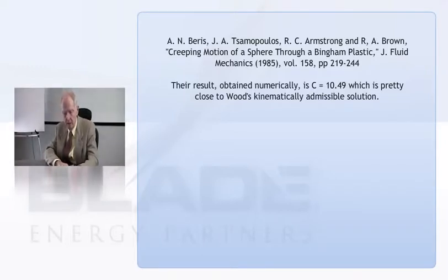And I think that's also reasonable, because when you're guessing a stress field, particularly in three dimensions, you've got to satisfy all the equilibrium equations, and that gets to be a little more difficult than doing it in two dimensions. So anyhow, my conclusion out of all this is that you're probably not likely going to find many three-dimensional solutions that nail things down much closer than the order of 2 to 1. That's just my own conclusion. That's really the only case I can cite for a three-dimensional.